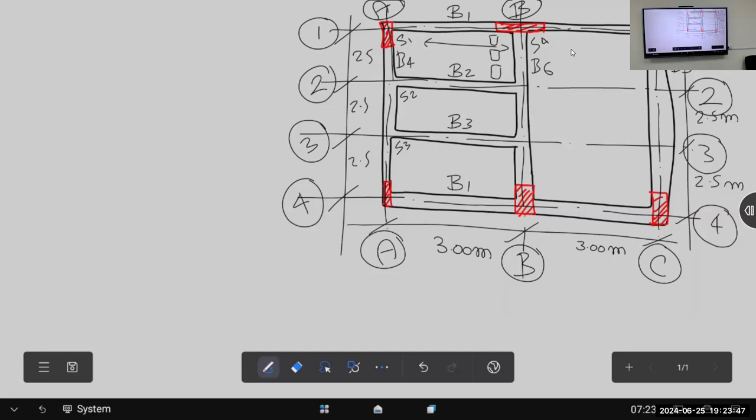If we are in slab number 4, how will the loads transfer to the beam? Because we study now the load path. If you are on the 60th floor and we are in this slab, I do not care about the 59th slab, because the load goes from slab to beam to column. Even at the highest floor, the column size is less than at the ground floor. Why? Because the ground floor accumulates all the loads coming from different floors. This is a very simple principle.